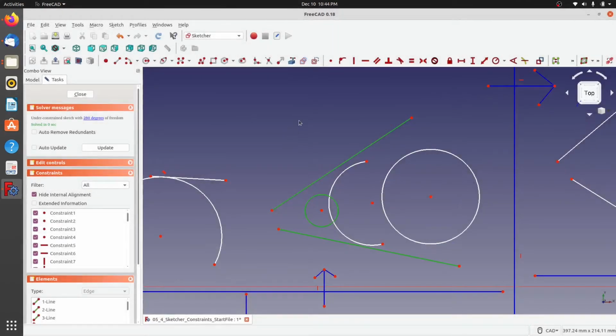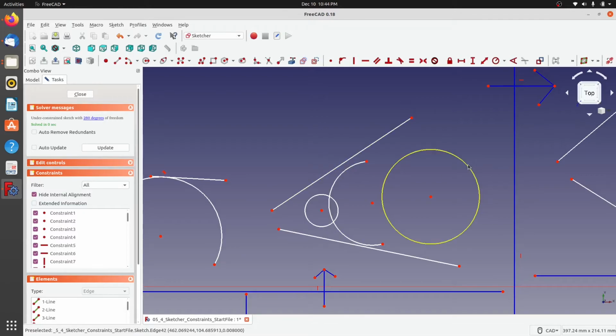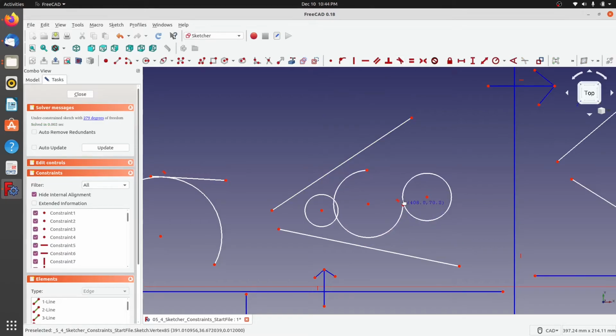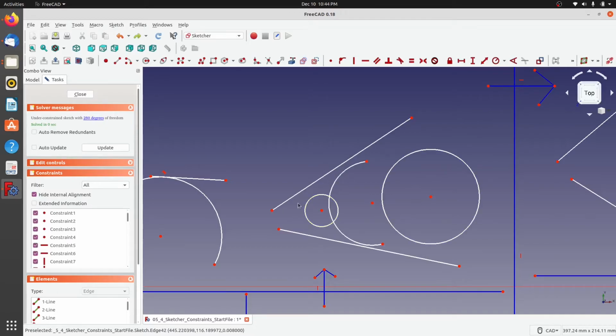So what does that mean? You need to select two curves, and then it can be tangential, but it will be tangential at one point. Okay, so if you make this circle and this arc tangential to each other, you can make them tangential and they will meet at a point. So that's what it meant. I'll hit Ctrl Z, come back to the original point.